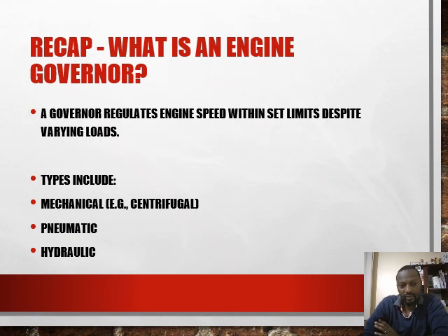So maybe just to do a recap and remind ourselves that a governor regulates engine speed within the set limits despite the varying loads. And it is very important in the diesel engine that the speed is regulated, so that the engine will not self-destruct as its components are quite heavy. In the reciprocating engine, if the engine is allowed to run on its own, it may run faster than expected.